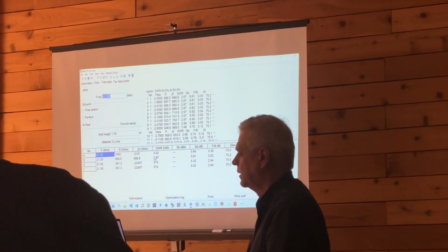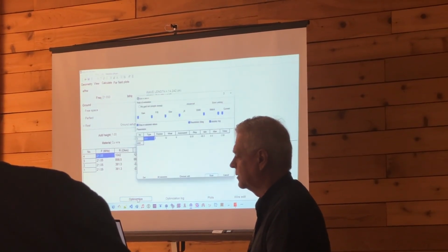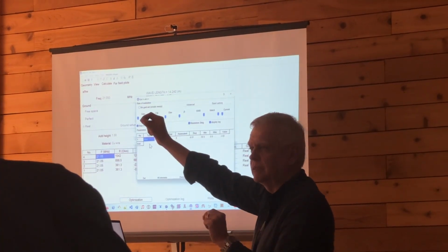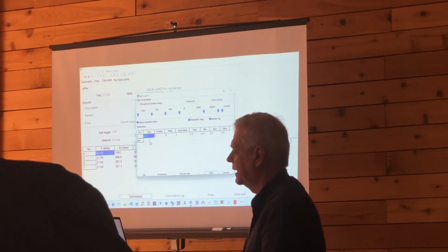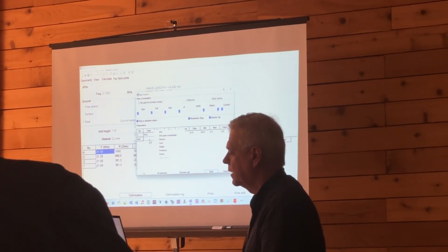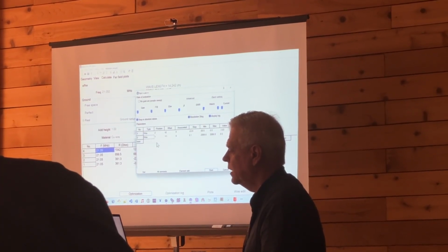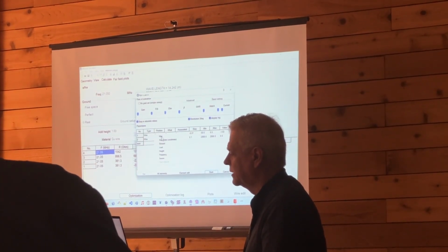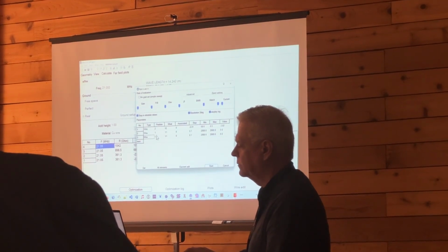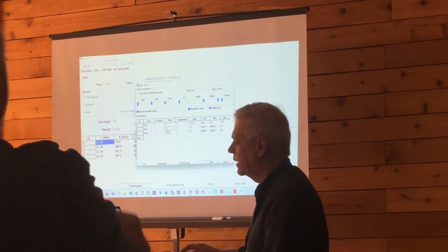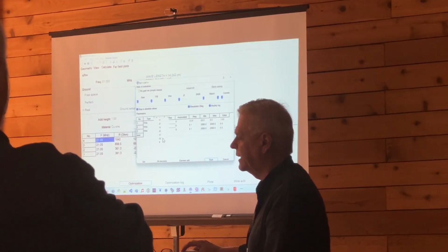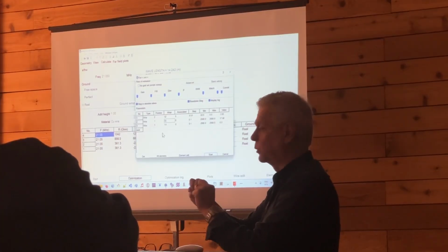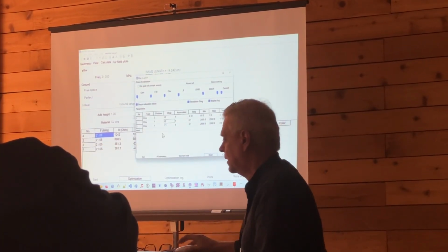That's still not good. Okay, let's go back to our friend optimization. And now what we're going to do is optimize the main element, the 67-footer. How do we do that? Again, click here and say wire. We're going to optimize one of the parameters of the wire. Might as well add another element of the wire here. Wire 1 is there, position 1. And what are we going to optimize? We're going to optimize X2. As the gentleman said, X2 is the displacement in the run, is what he called it, in the X direction. So that's what we're going to say.